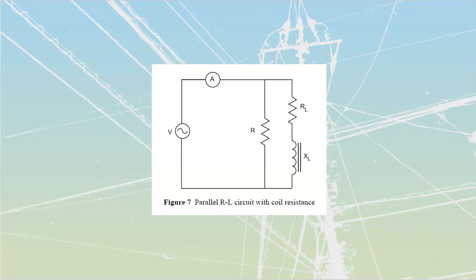The last section of this talks about the fact that sometimes we have got a practical inductor placed into our calculations. Theoretical inductors exist only on paper. Practical inductors are made out of copper, therefore they have got resistance inside of them. Most cases we see them drawn with a set of dotted lines circling around them like that, which indicates that they're part of the same component. We can't actually physically measure the resistance separate from the XL, the reactance that we would have inside of there.